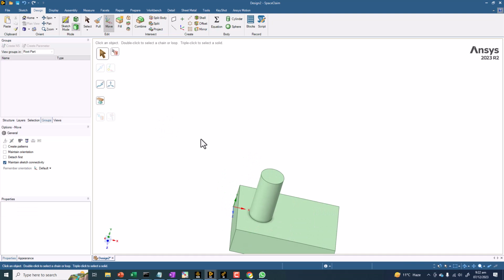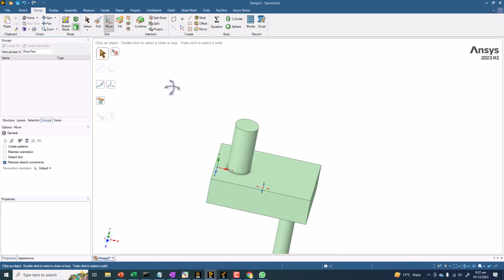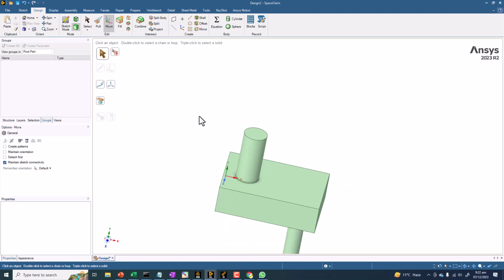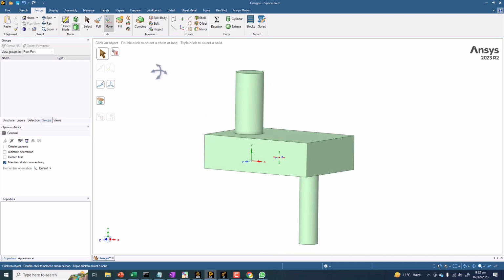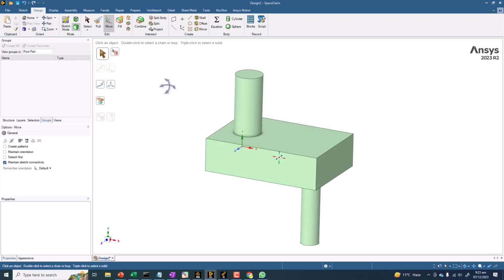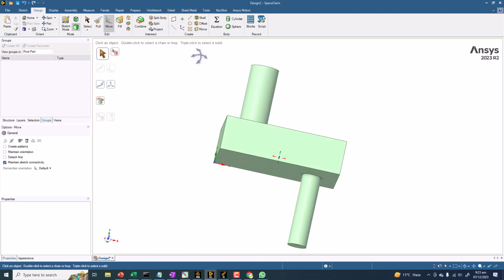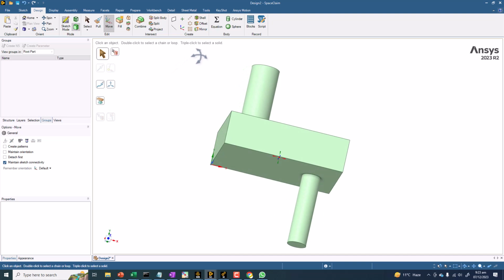Okay, so now the method we are going to use in the ANSYS meshing is the multi-zone meshing. Although it says that the multi-zone mesh does not require any type of geometry decomposition, if you do that, it will be much easier to make the required meshing in ANSYS meshing. But for the sweep meshing, definitely we have to decompose the geometry to very minute details, like we have to create all the blocks ourselves. But in the case of the multi-zone method, we have to create the cylindrical shapes at least.